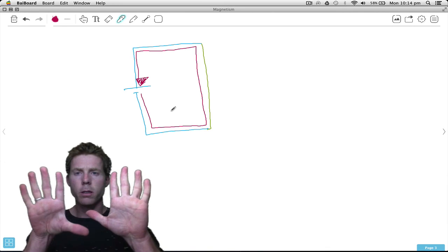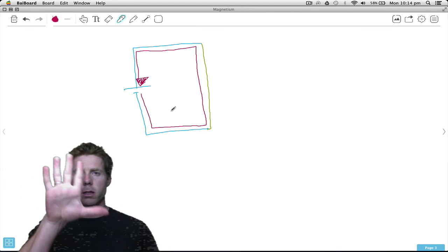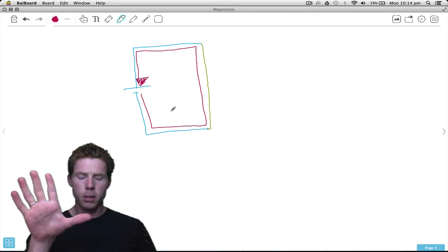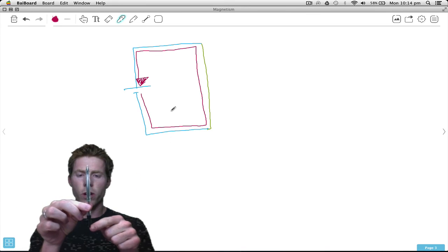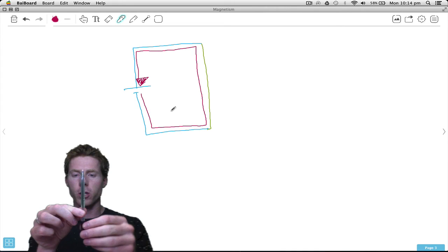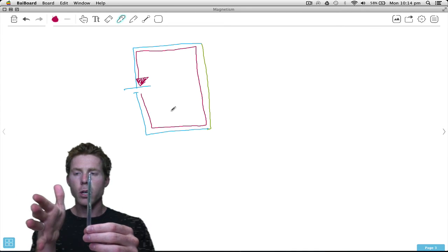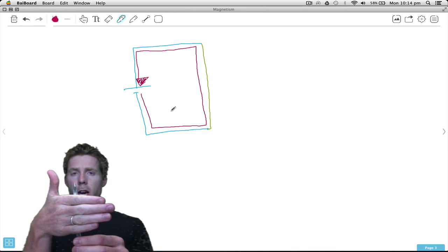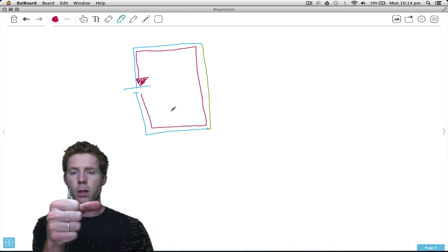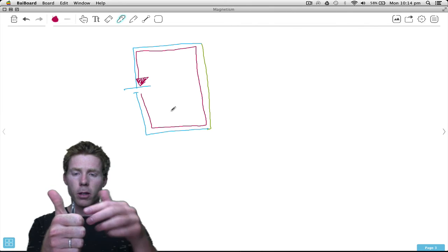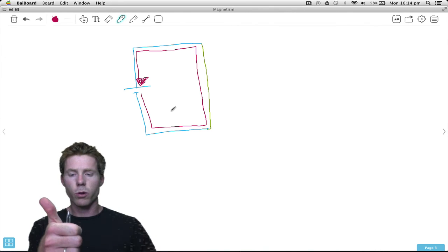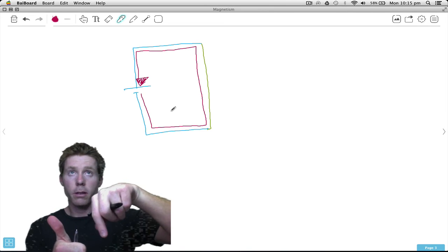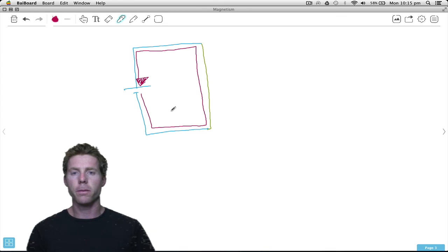So you get your two hands, figure out which one is left. In this case, it's this one, because it's got an L for me. So the left-hand grasp rule means I'm going to get my wire. Electrons are traveling from bottom up through the top. I'm going to grab it with my thumb pointing in the direction those electrons are flowing, so pointing up, and then I'm going to grab that wire with my hand. Now my fingers actually show me the direction the magnetic field is rotating. In this case, it's rotating in a clockwise direction as I look down on it.